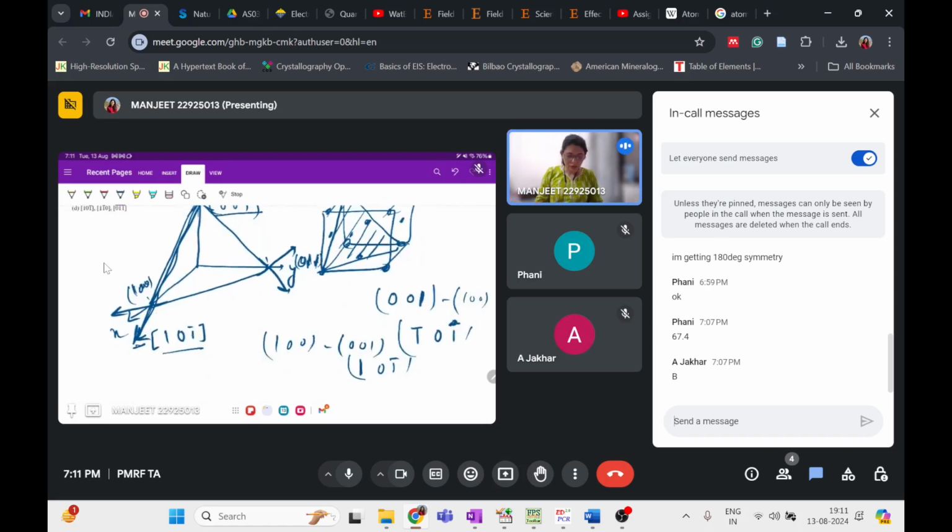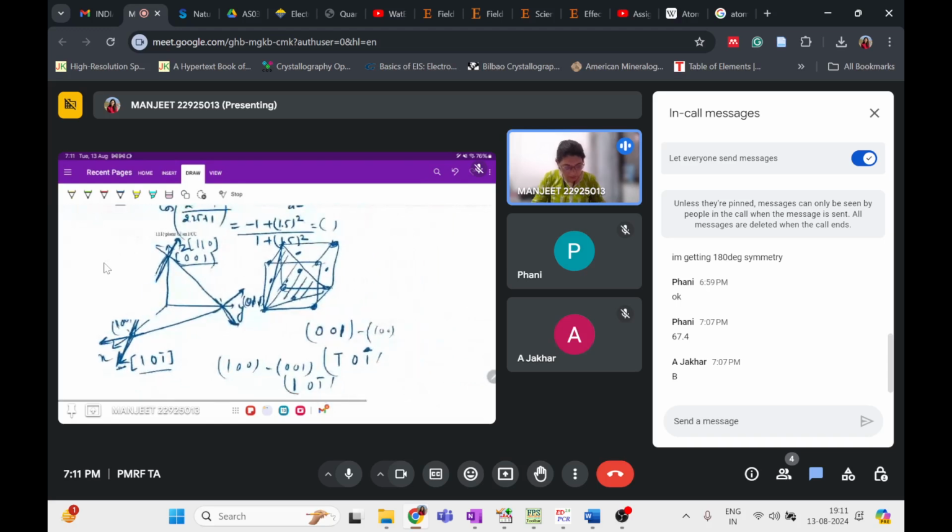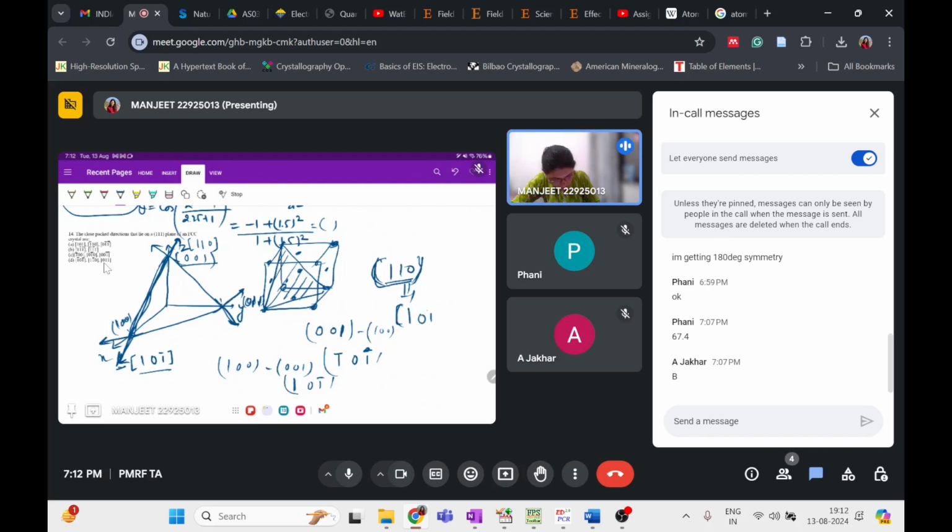Similarly, you can find the other ones here also, because you know the coordinates and you can find the directions. Okay, so if you find them, you will come up with six different sets. If I'm considering this plane now, (111), these are the only sets of this family. So for this one, the corresponding direction will come out to be [1 1 0] and [1 0 -1].